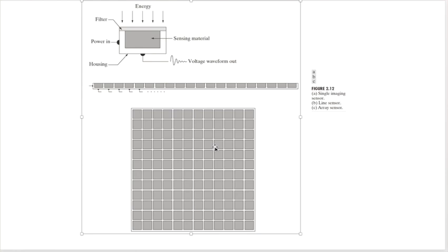The other big thing you'll have on these is that the filter is not perfect. Right? I might say that I want something that lets through red light, but it doesn't perfectly let through red light. And it doesn't perfectly block out green or whatever else. So what it will do is it's going to have what's called a quantum efficiency. How much does it let through? Okay? And you want it to let through a lot of your red and block a lot of the greens and blues and infrareds, but you will not get perfect. So you have to look at that quantum efficiency. That's really important when you go to astronomy or medical apps.